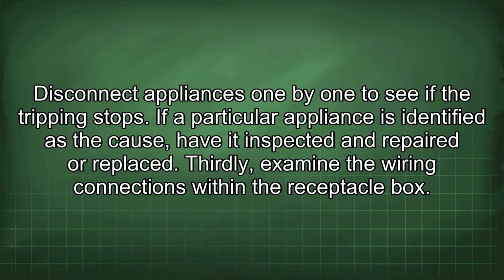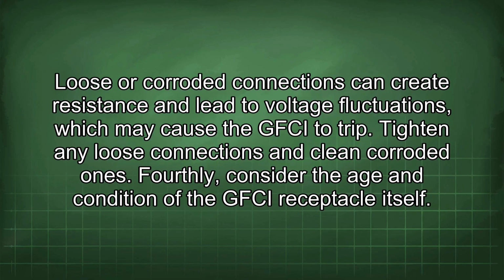Thirdly, examine the wiring connections within the receptacle box. Loose or corroded connections can create resistance and lead to voltage fluctuations, which may cause the GFCI to trip. Tighten any loose connections and clean corroded ones.